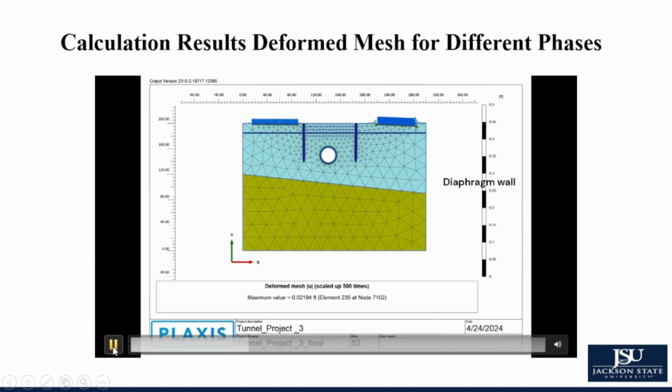And then in another phase, we started the excavation because we need to excavate 20 feet, but we can't do the excavation altogether. So at first we did 5 feet excavation, and for that you see that the soil is going a little bit upward for the unloading. And then we did the second excavation, and you can see that the soil is going a bit upward again. The soil height is less actually at this moment, so this height is showing that it's going upward.